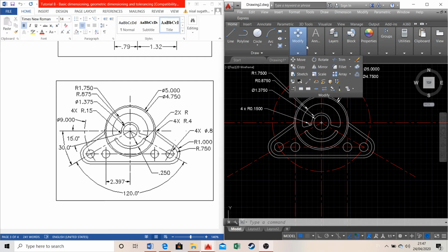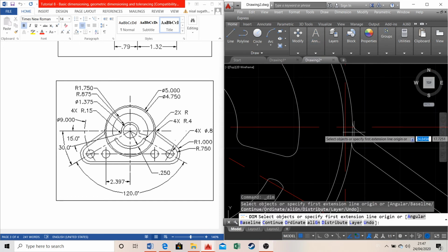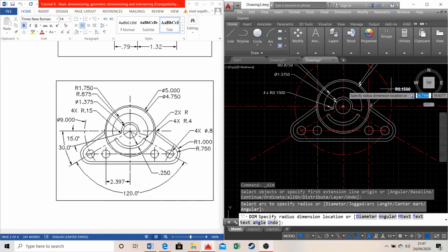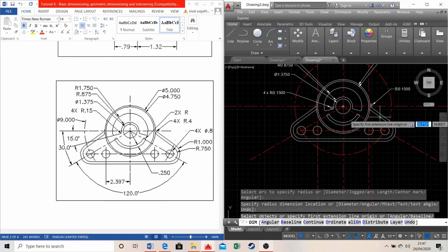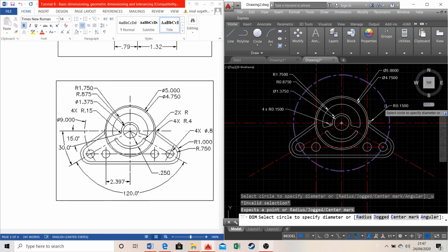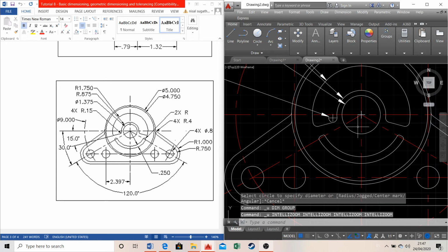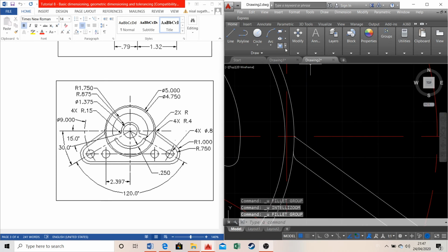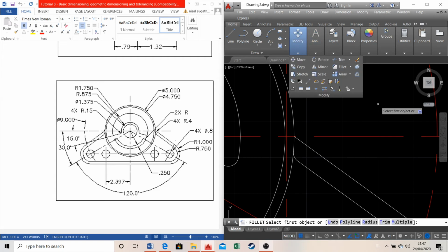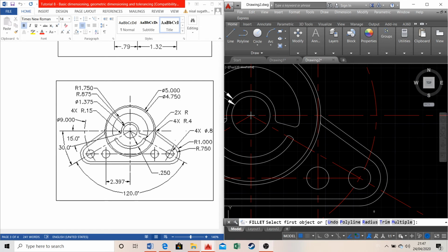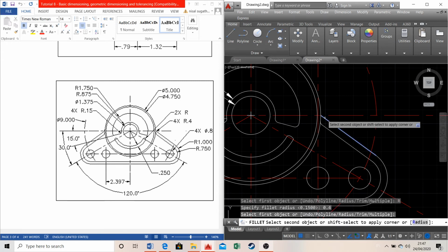So again, you can go to dimensions. Okay, so it's 0.15, that's wrong. I'll have to redo the fillet. The mistake I made is I entered a fillet here and I assumed that that was going to appear here as well, so I'll have to change the radius by selecting the radius and entering 0.4. Yeah, so I've entered the radius as 0.4. Now we just have to select the two lines.